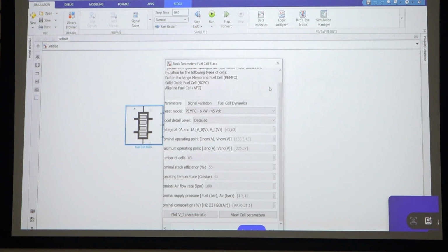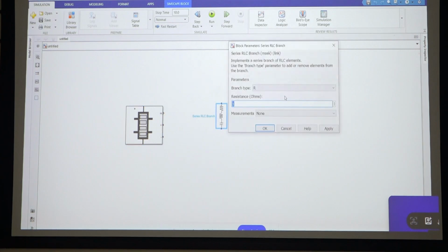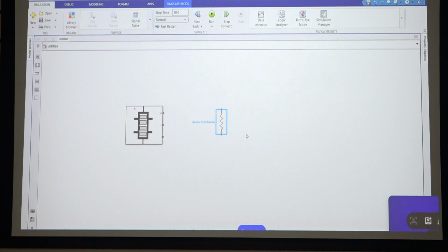According to Ohm's law, we can put any value, but we are putting 45 over 1 here. For example, this is the resistance value. Click OK. Then if we go close to the terminal, positive negative, it automatically comes, and you just drag and connect to your other points. Just drag it to the other terminal. It is a very simple circuit.